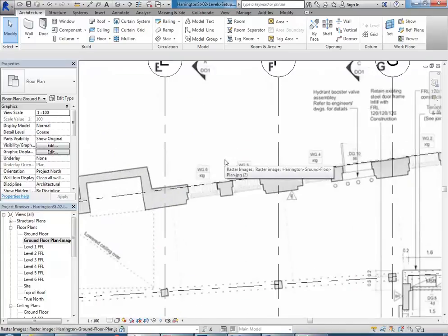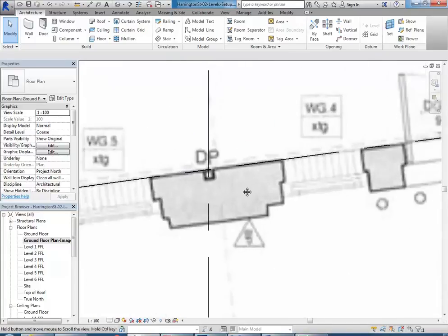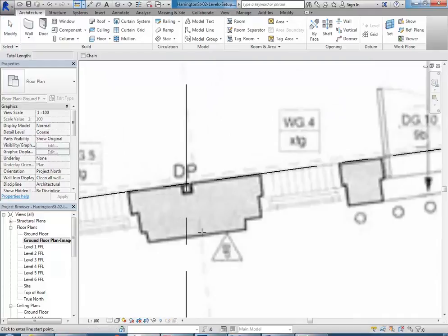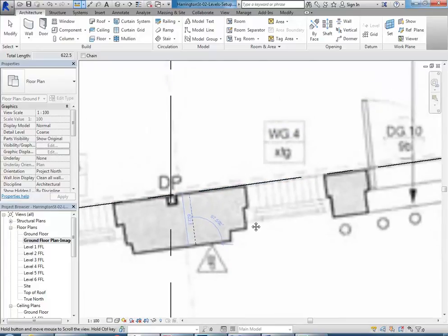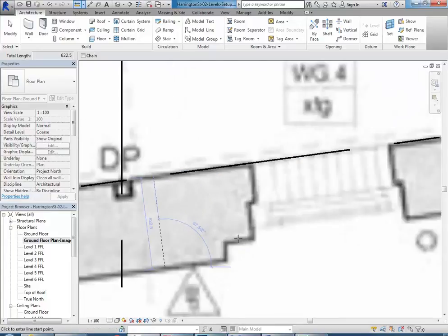So looking in the floor plan, you can see, as I was saying, the walls are thicker than normal, so they're not just double brick walls. They would have an extra skin of brickwork, most likely, so they'd probably be solid brick with a cavity as well. So solid brick on one side and then single skin on the other, maybe. So what is it, 600 or so there is the thickness. That's including the pier. Let's maybe measure it from another point. So from there, without the pier, it is